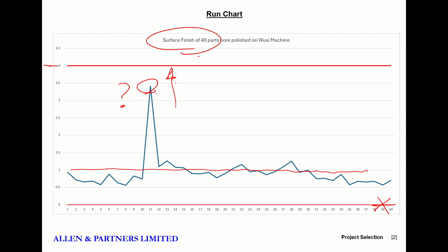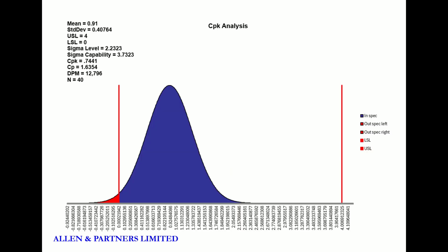So there's the performance. Now we've just set it up. We could just put this machine into service and go, there you go, it works, there's our settings. But that's for just 50 pieces, a sample size of 50 pieces at the beginning of this. Why don't we see if there's better settings? So that's what we're going to do, and we're going to run a design of experiments in order to find that out. So there's the current performance.